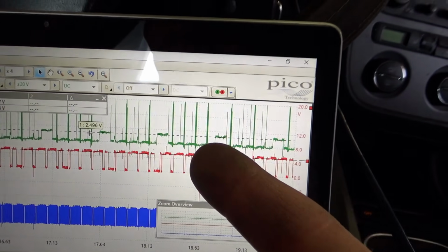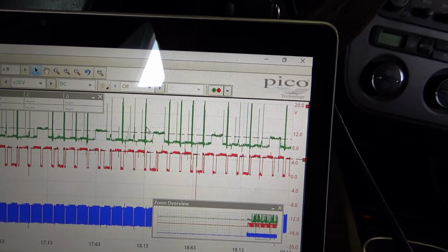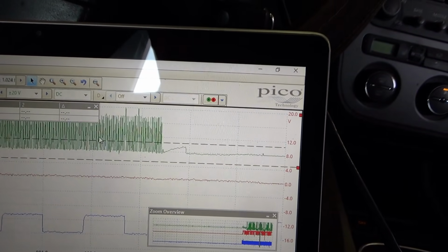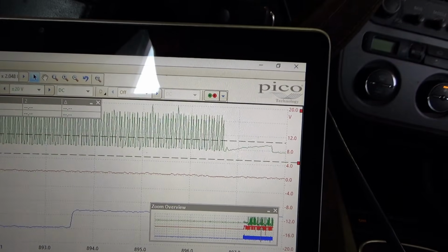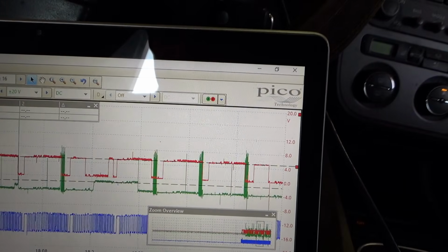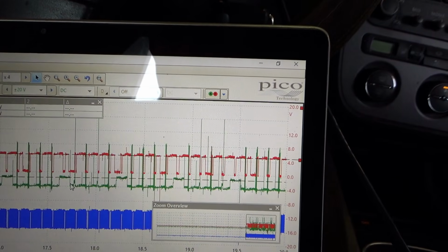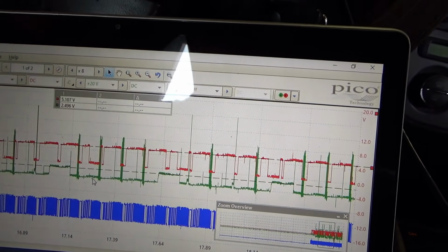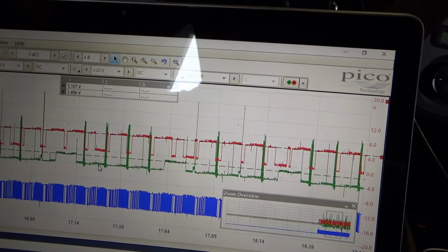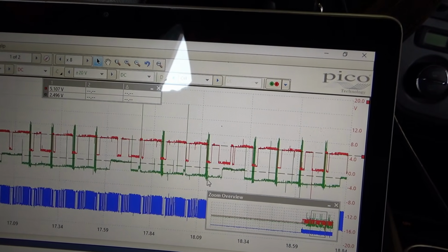We can put a current clamp on the feed wire and then see when this injector is firing, because the feed is common, so it's going to see buzzing. One, two, three, four. Now, something doesn't make sense. When does this thing repeat? Does it repeat every cam revolution?